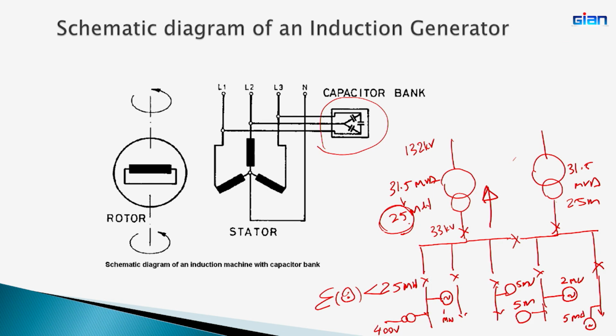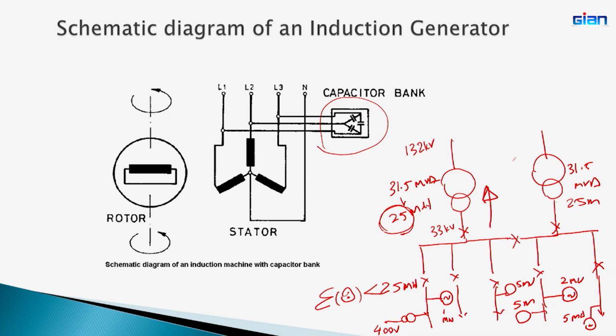Now, you go with a proposal: I have such and such a place, a mini hydro opportunity of 5 megawatt, I am interested in developing. So, you first have to make an application to the utility to check whether your nearest grid substation has extra capacity available, right. They will check whether the system is already full of mini hydropower plants, then they will say sorry, we cannot grid connect this, because the substation capacity is not enough. This has happened particularly in hilly areas, where there are many hydro opportunities and they have been developed, but the grid substations are limited, right.